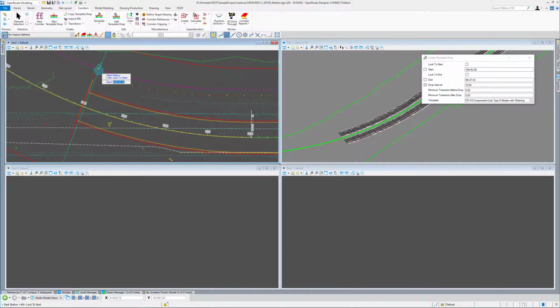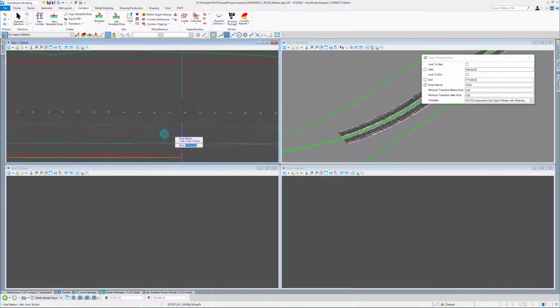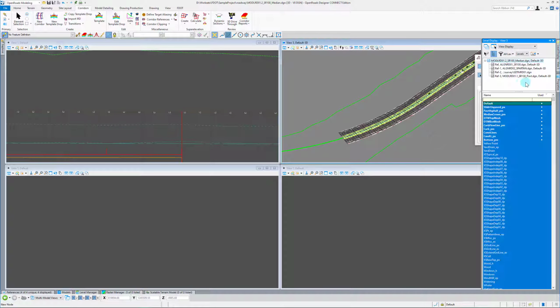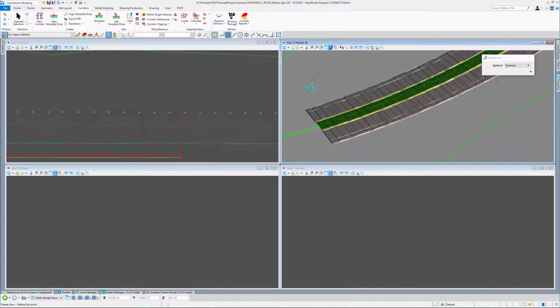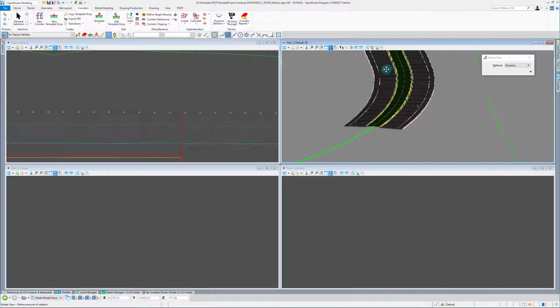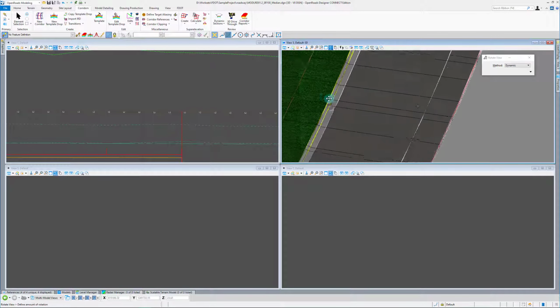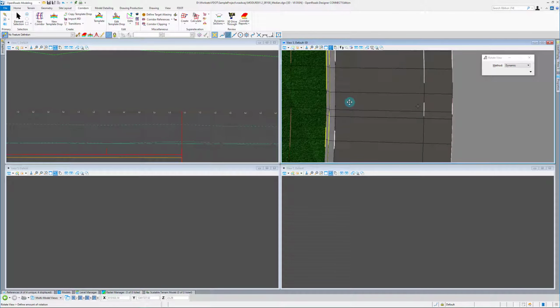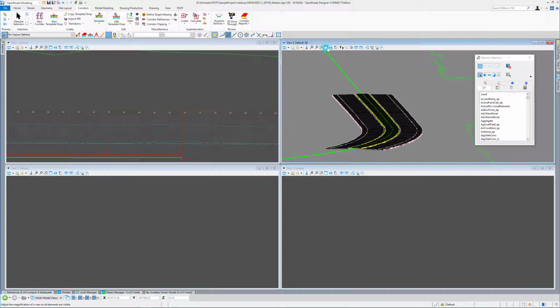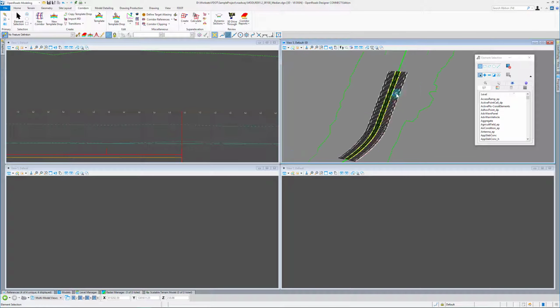And we're going to snap to the same limits as our previous template, our previous corridor. Do a 10 and pop that in there. So then I can come in here and turn off my top and bottom mesh so you get a cleaner view. And we have our median. So you can see that median is following that edge of pavement line. We got our crowned median. Everything's drawn. Looks pretty nice.